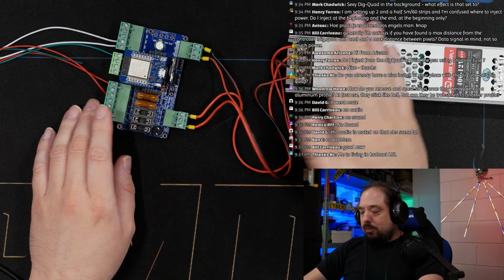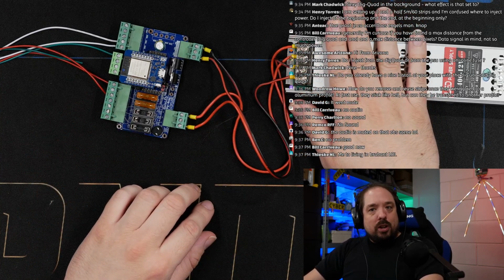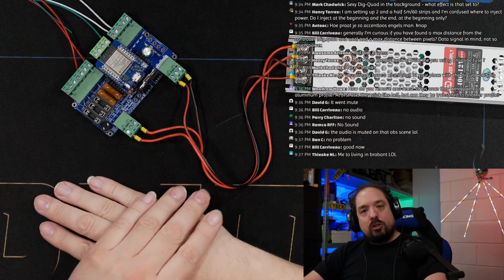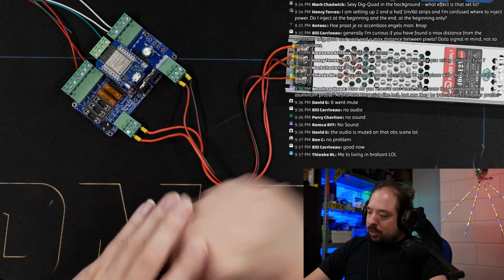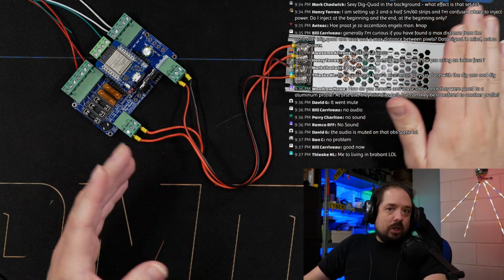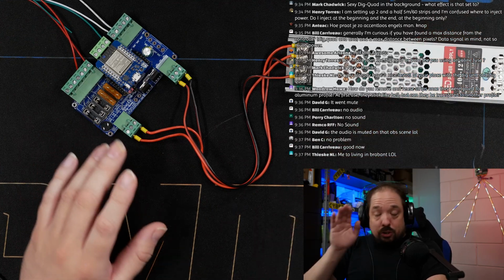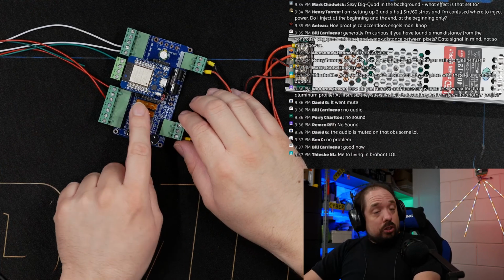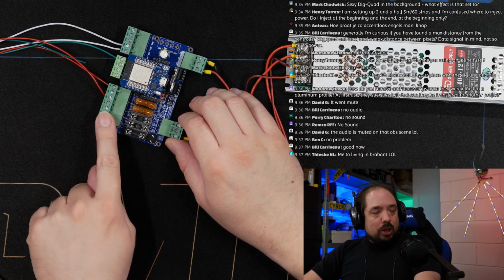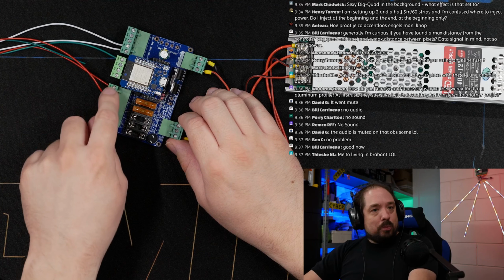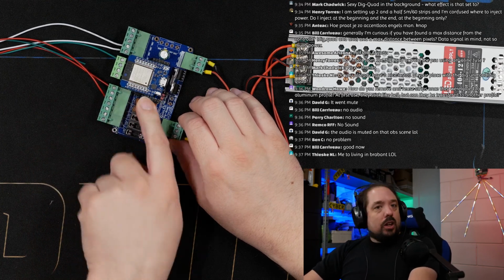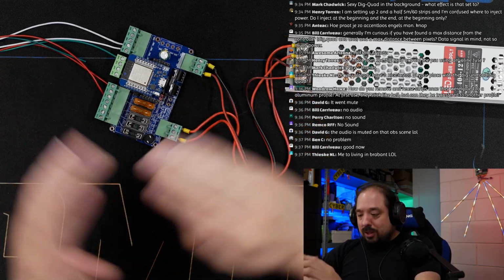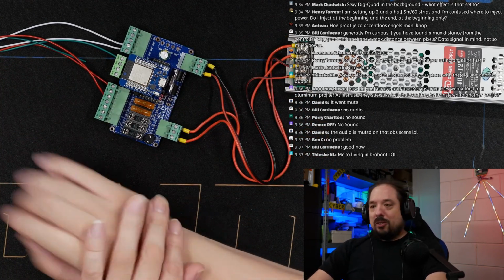If you have, let's say, a 30 amp power supply, putting a 30 amp fuse between the power supply and whatever load it's providing doesn't do anything, because the power supply has OCP, over current protection, anyway. So that doesn't make much sense. What does make sense is if we have 7 output terminals and we have the 5 fuses, and some terminals use 1 fuse, you fuse for what's behind that in regards to wires and LEDs, and then it's a proper situation.